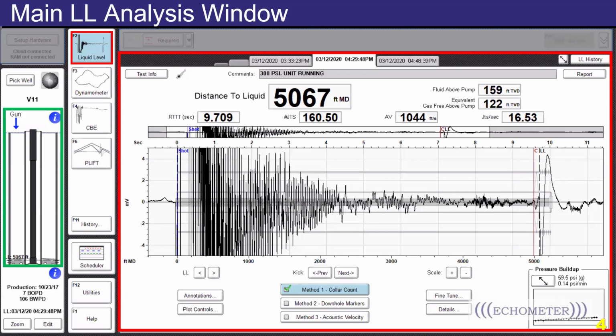On the left-hand side of the screen, we also have the wellbore schematic. It is drawn based on the information that we input, like tubing, casing information, perforations, and rod string if it's a rod pump or a PCP well. Depending on the type of well, we have a different drawing, but on that plot we will also have an update of the liquid level calculation, as we can see down here. We have some drawings showing the liquid level depth and the liquid distribution in the wellbore.